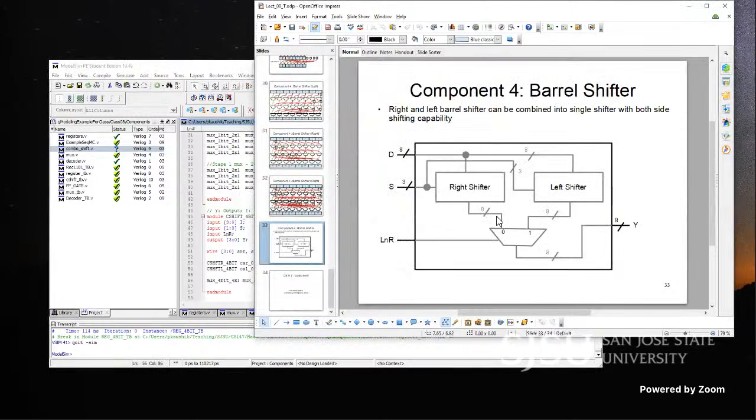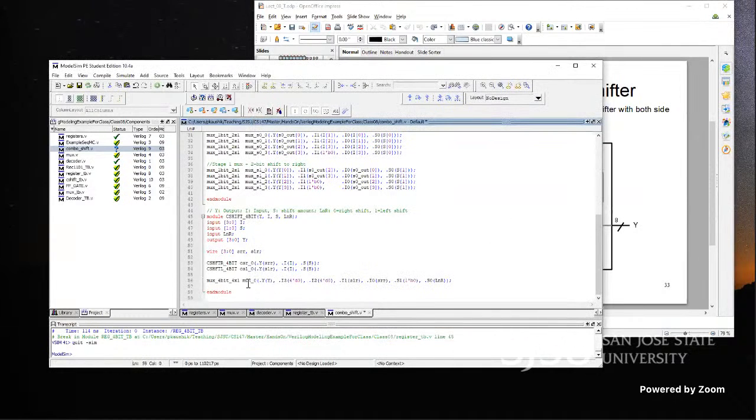So as if we are using a 4-bit 4x1 multiplexer, but one of the higher selection bits is tied always to 0. It is never going to select between I2 and I3. It will always be selecting between I0 and I1. And thus, I3 and I2, I just grounded them, basically. Electronically saying I grounded it, logically said I connected it to 4-bit zeros.